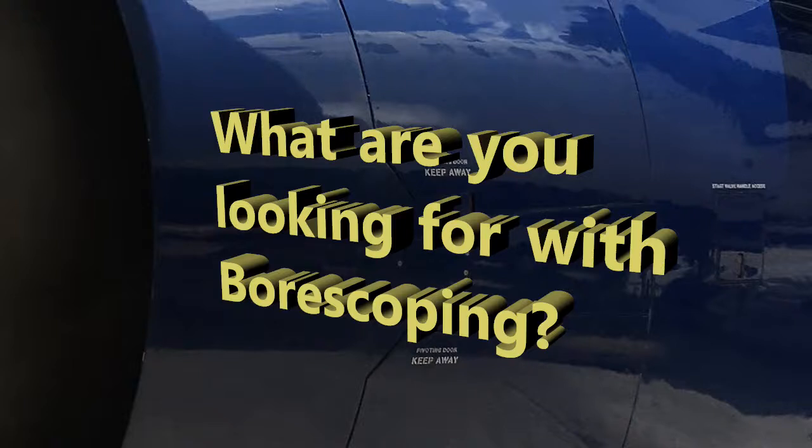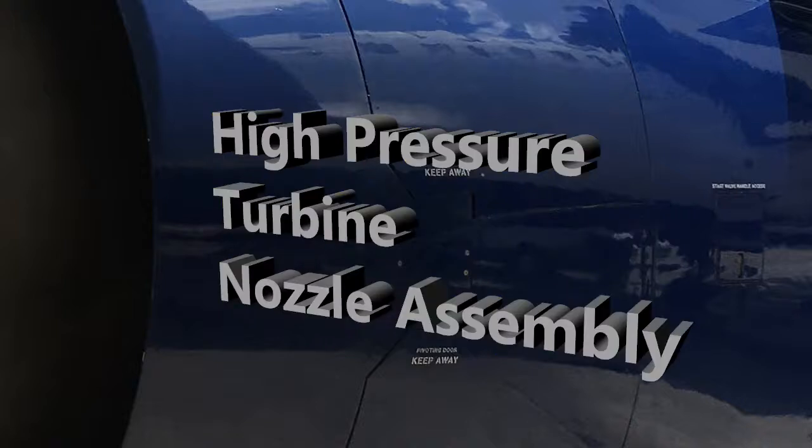Okay. You also have the high pressure turbine nozzle assembly. You can do inspection there as well, and you have ports in that area. Here you've got ports at the 1, 3, 6, and 10 o'clock positions, and those are located immediately in front of the fuel manifold. So the high pressure turbine nozzle bore scope ports are at the 1, 3, 6, and 10 o'clock, immediately in front of the fuel manifold. You may want to underline that. That's actually a question that you probably are going to see on a test.